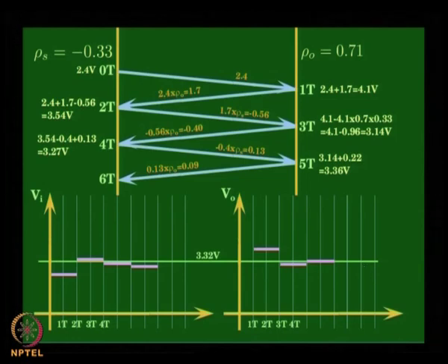Now, this is a serious problem, because if the overshoots or the undershoots are significant, here it could switch off the subsequent stage. You could have bouncing effects, you could have double pulsing effects because of all these reflection problems.